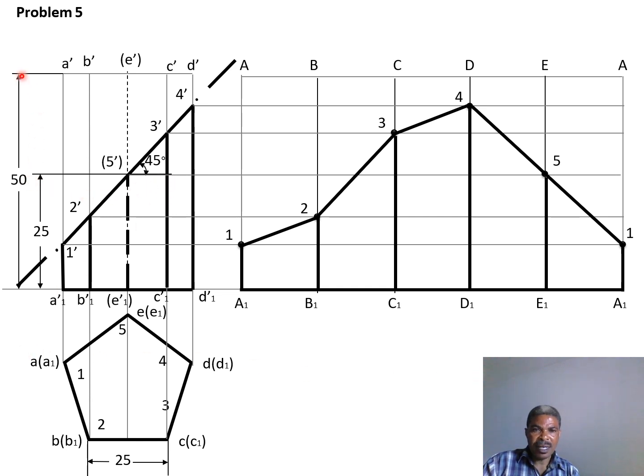So you can see, after you have drawn the plan or top view of your prism, you need to construct the front view first. From your front view, given that you have indicated where the axis center line is, you need to locate the center of your axis from the bottom.